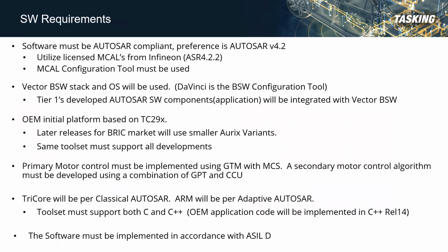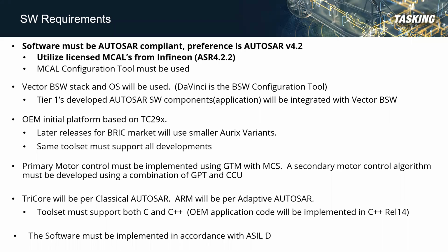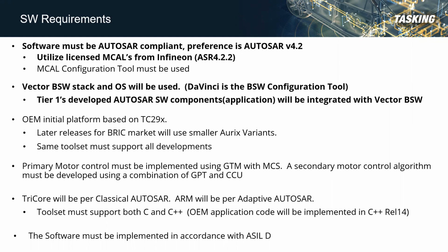So moving on, we've addressed our hardware requirements. Let's look at our software requirements. The OEM is specifying that our software must be AUTOSAR compliant, and they are specifying AUTOSAR version 4.2. They're also requiring that we use the BSW stack provided by Vector.